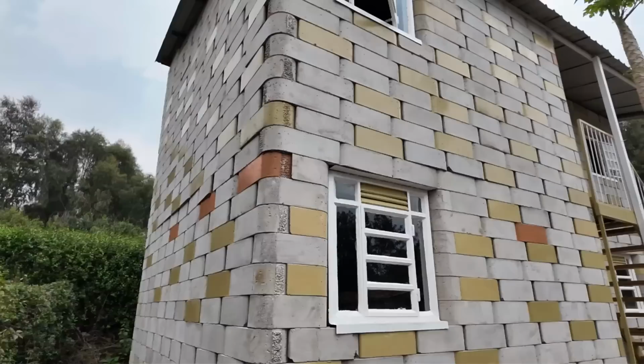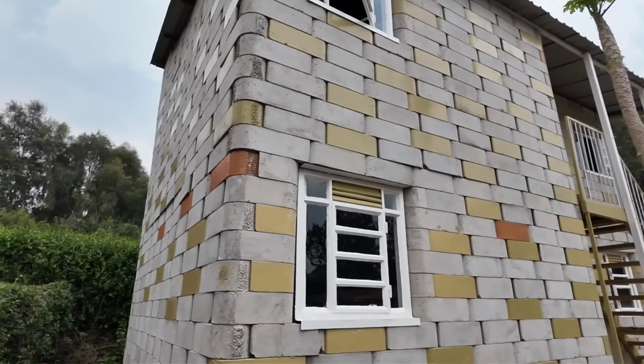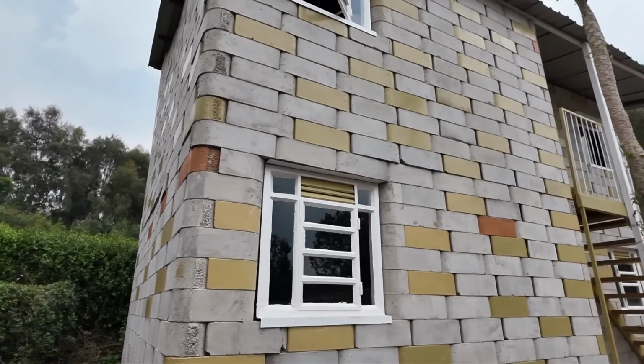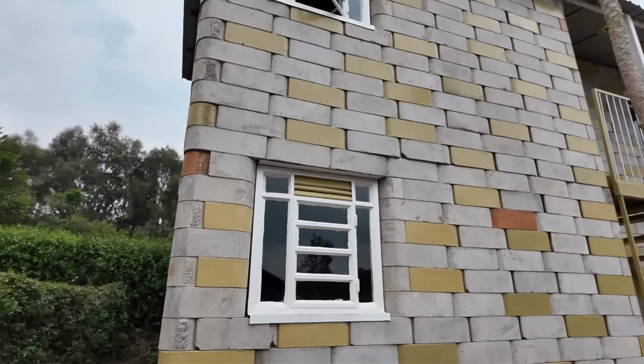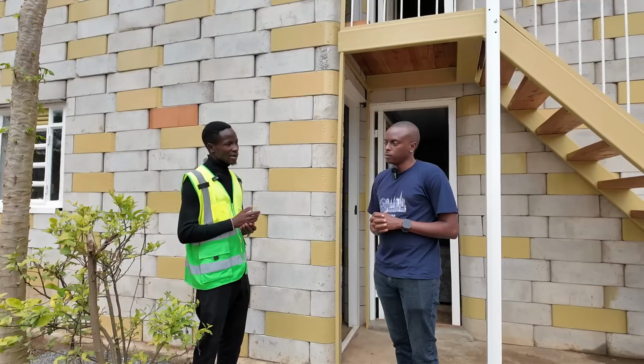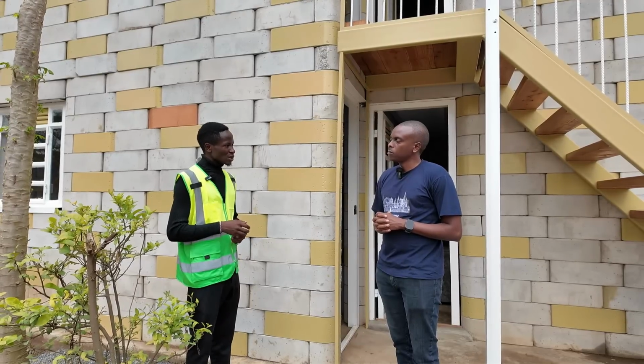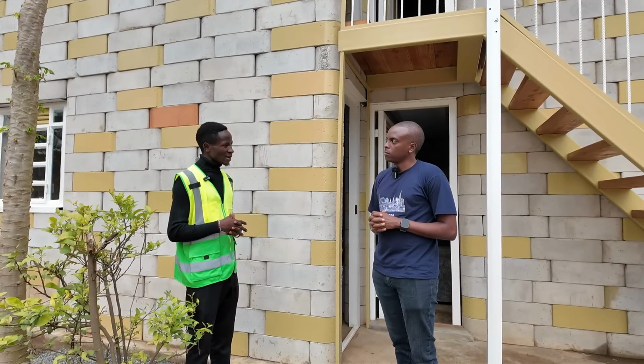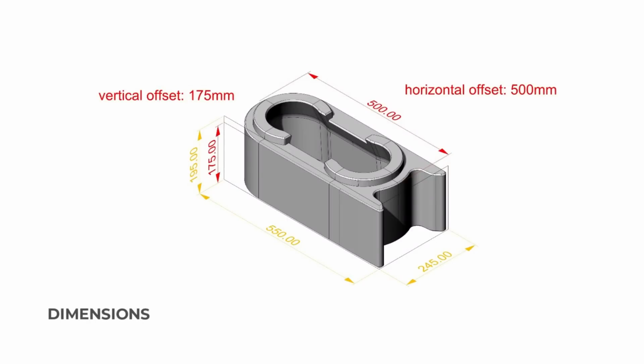Because the blocks are hollow, do they offer thermal regulation and noise regulation? Yes, that is also a very advantageous aspect of the twist block. The hollow nature of the twist blocks allows it to trap enough air. As we all know, air is a poor conductor of heat, so it is able to microclimate the temperatures of the internal from the temperatures of the external.